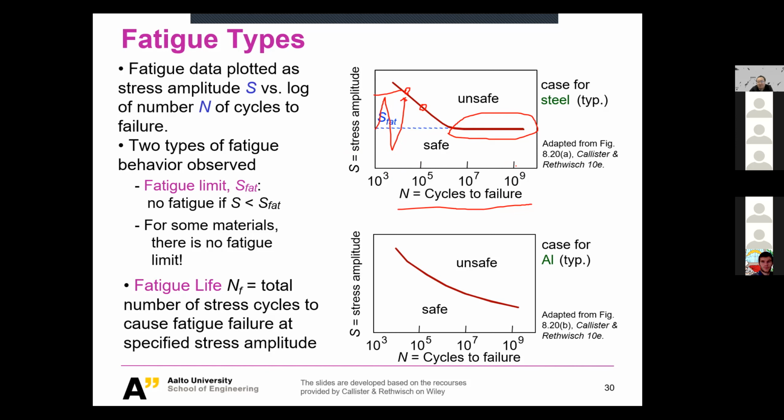Maybe you wonder, wow, that's a miracle, right? But actually this is also not true, because recent studies are developing. Actually, this is part of your room phase studies back in your master program, right? Because they can perform very high cycle fatigue, something with 20K or 50K hertz for a test. Then you could reach this kind of billion cycles, because for 25 hertz, it probably takes months or years to reach this kind of cycles. That's why people think, okay, that is going to last forever.